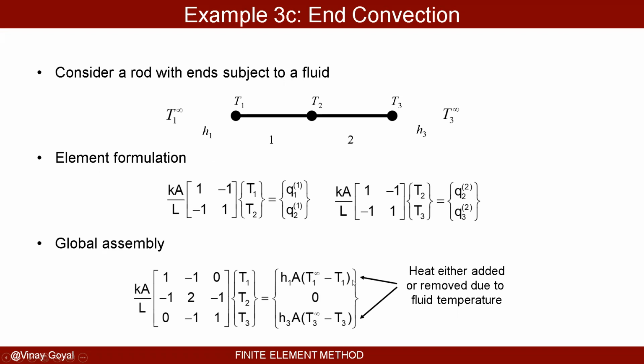This boundary condition is a heat flux. Remember, I can lose heat from here, according to the problem statement, to the medium. And the formula for heat flux is h1 times A times (T1 of the medium minus T1 at the node). So very clearly that works out. I have to put Q as those values because in this case, that is what is going on at those nodes. I'm losing heat to the medium at these nodes. And that's why this is correct.